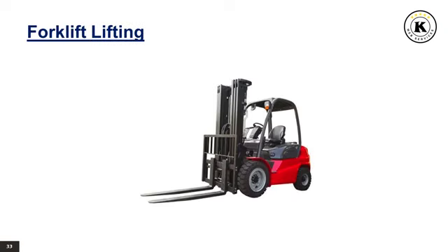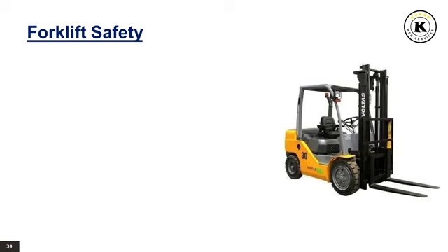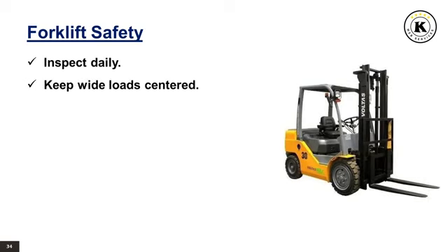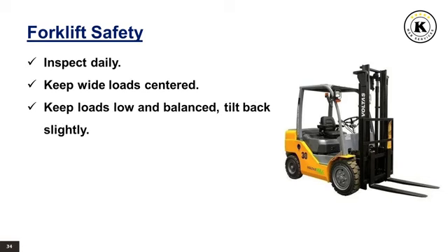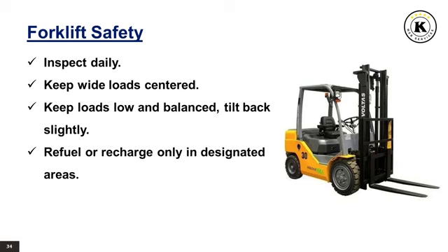Forklift lifting. Forklift safety. Inspect daily. Keep wide loads centered. Keep loads low and balanced, tilt back slightly. Refuel or recharge only in designated areas. On slopes, travel with load uphill.